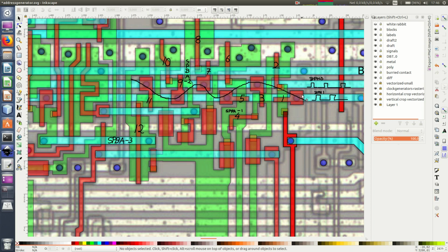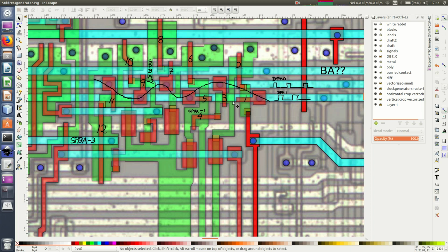So what you have here is a dynamic latch. Every time it passes here, it's delayed half a cycle, because these 2 clocks are half a cycle apart. They have the same frequency, but they are sort of shifted apart. So we will simulate this. You can see it. The sprite buffer comes in here, delayed by half, full, 1.5, 2, 2.5, 3. So it's delayed by 3. That's what I mean by 3.